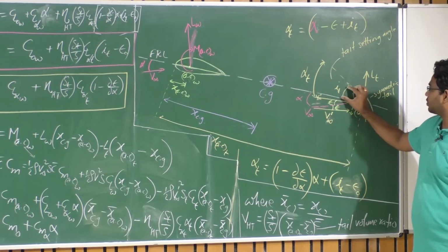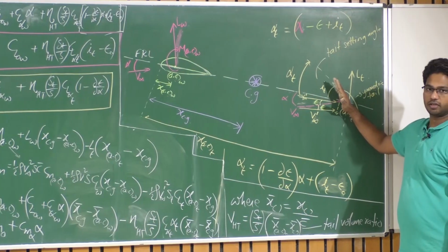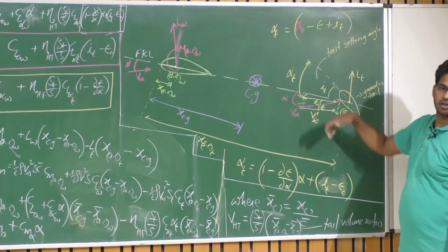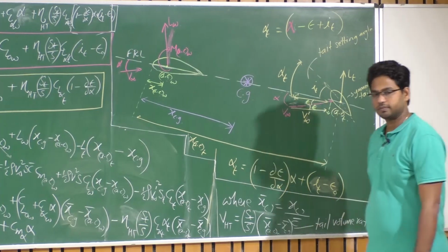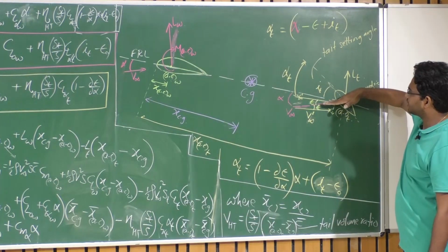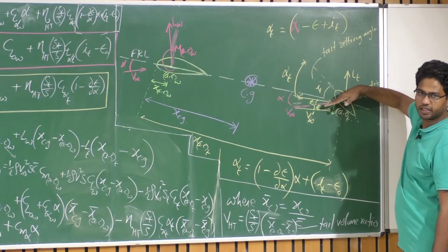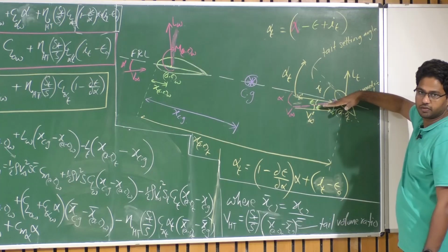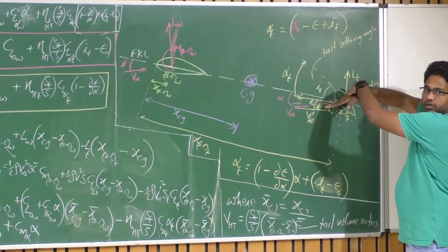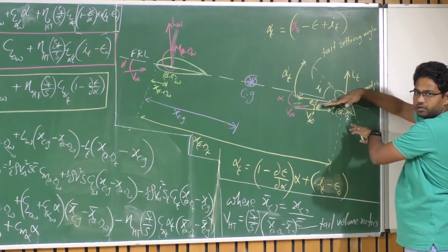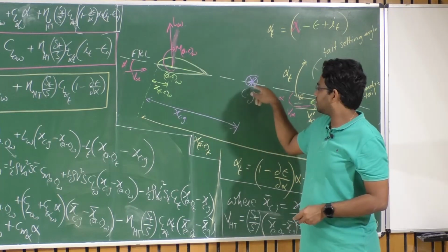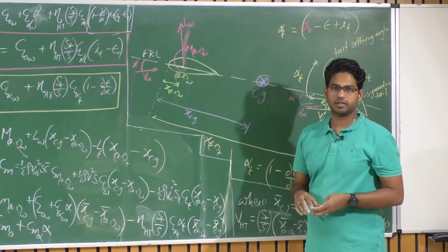So i_t is positive when inclined above the fuselage reference line, right? It is negative when it is inclined or oriented below the fuselage reference line. So that means you need to set your tail with a negative orientation with respect to the fuselage reference line. By doing that, when there is a flow, you are obstructing the flow, so there is a downward force. This downward force, even at zero angle of attack, will create a pitch up moment about the CG.